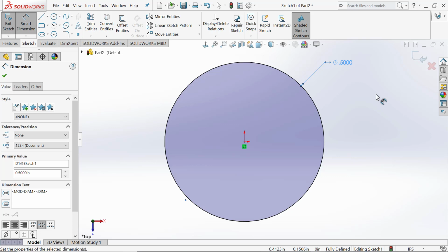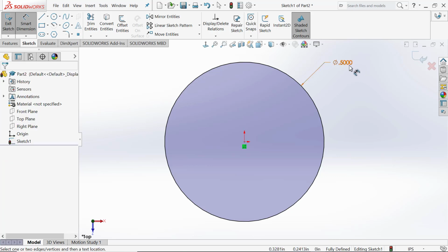0.5. I have it on the board here. Right click, top plane, start sketch, start the circle tool, click on the origin, slide over, click a second time, turn off the circle tool, launch Smart Dimension, click the perimeter, draw away a little, click a second time, type in 0.5, click the green check, and you should have this.